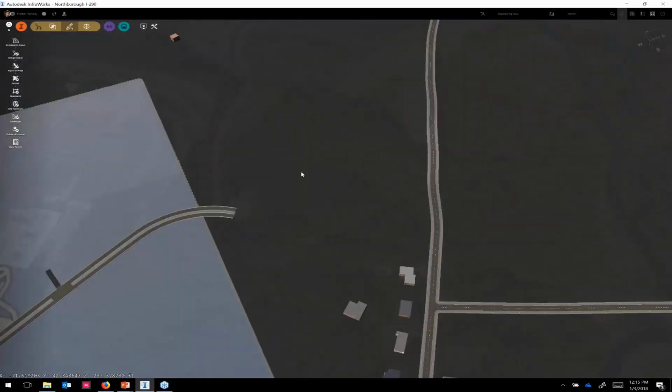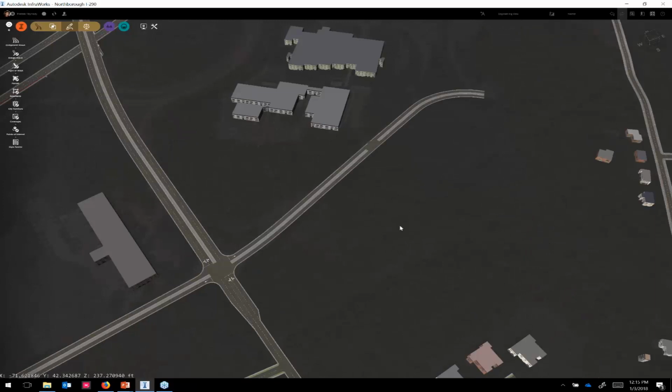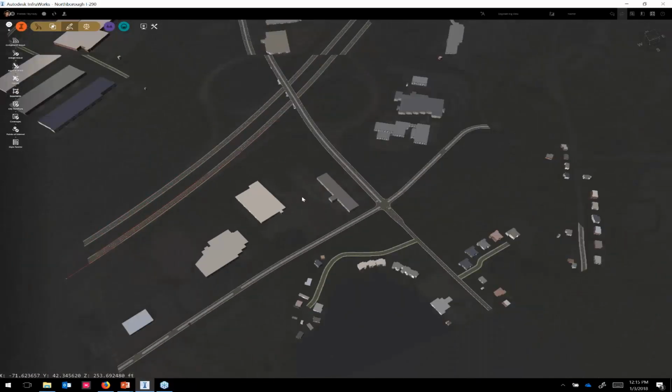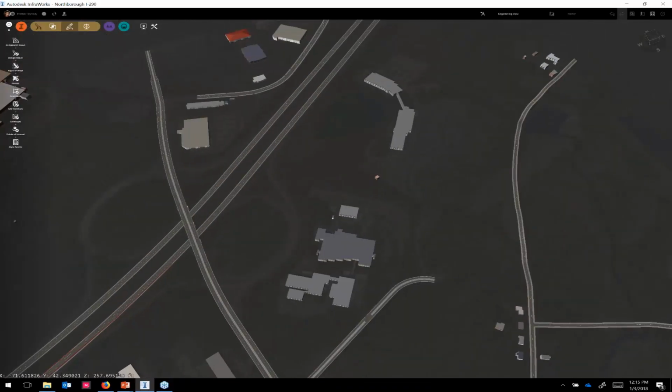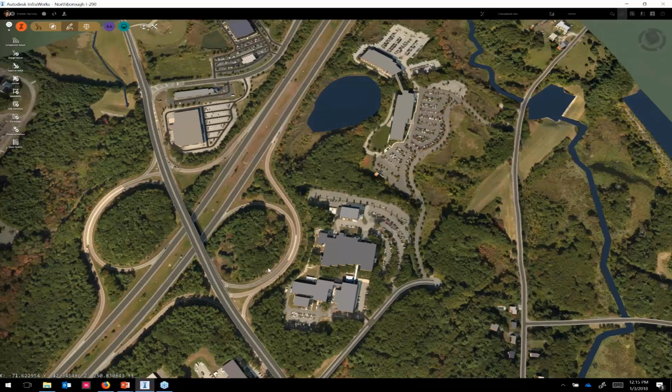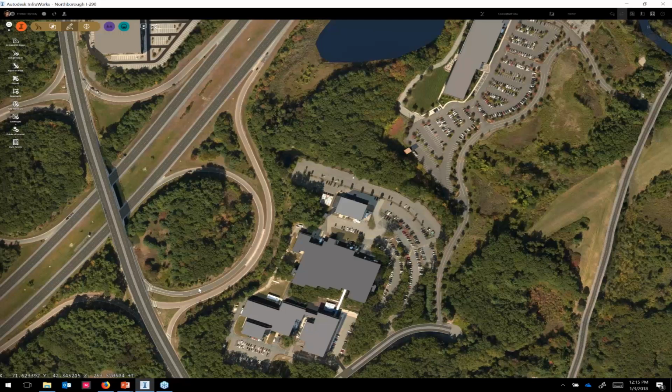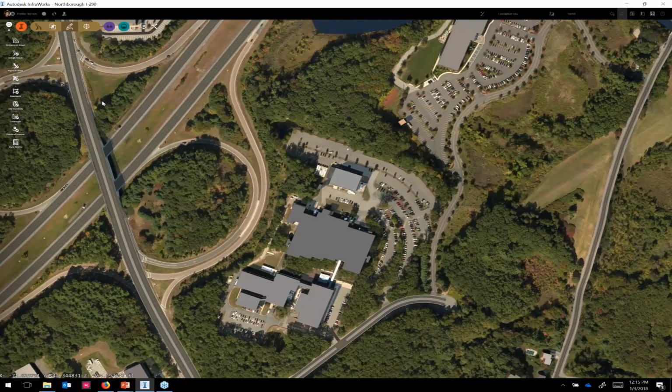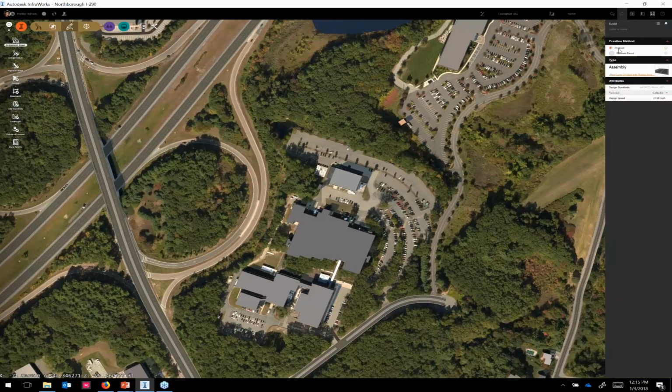Now let's talk about the enhancements itself. So going back to this space here, I'm going to switch to the conceptual view so I could see what needs to be done. So I'm trying to sort of recreate this ramp scenario here, right? So I'm going to go ahead and click on Component Road tool. And what we have today in the software is by default PI-based layout. PI-based layout meaning I click a point, I define a point of intersection, and define another point of intersection.